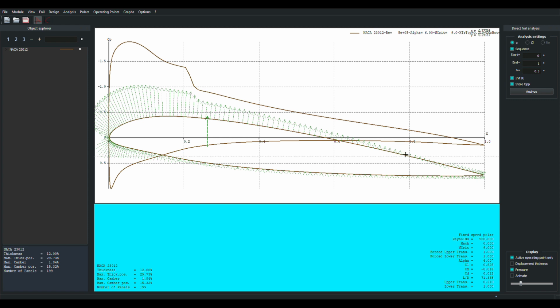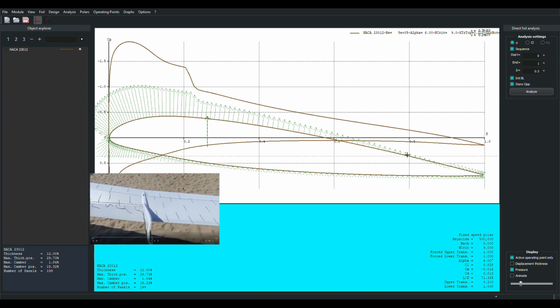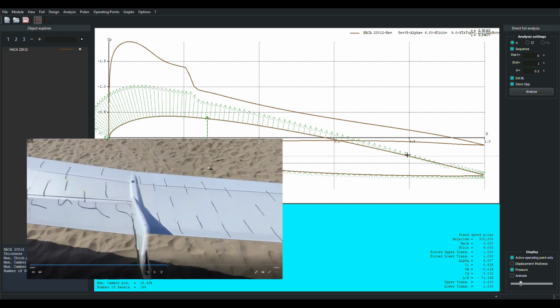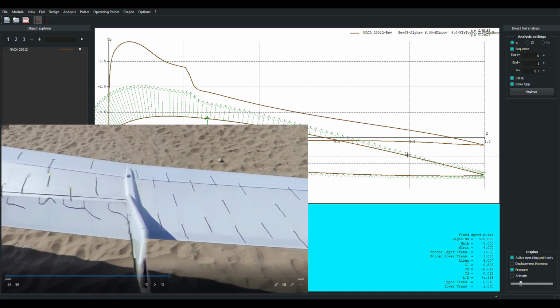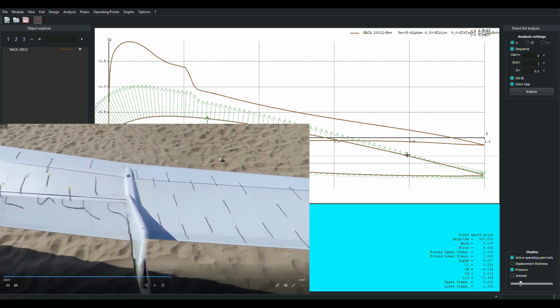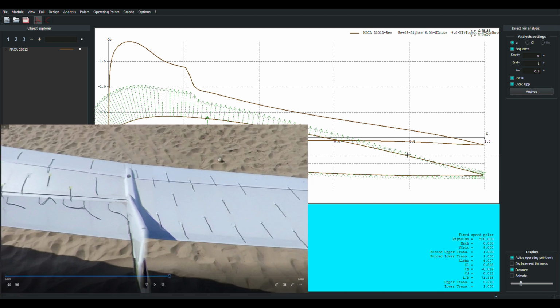And in fact, if the conditions are bad enough, as we've seen on my wing when we were out with the initial tests, and I'll put up a picture here so you can see that, they literally turn 90 degrees, turn the corner, and head out to the wingtip. In fact, the first time we saw that, it's like, holy smokers, how is it that flow that was going this way can, in such a very short distance, turn 90 degrees and head straight out to the tip? And that really sucks, and we got a problem.